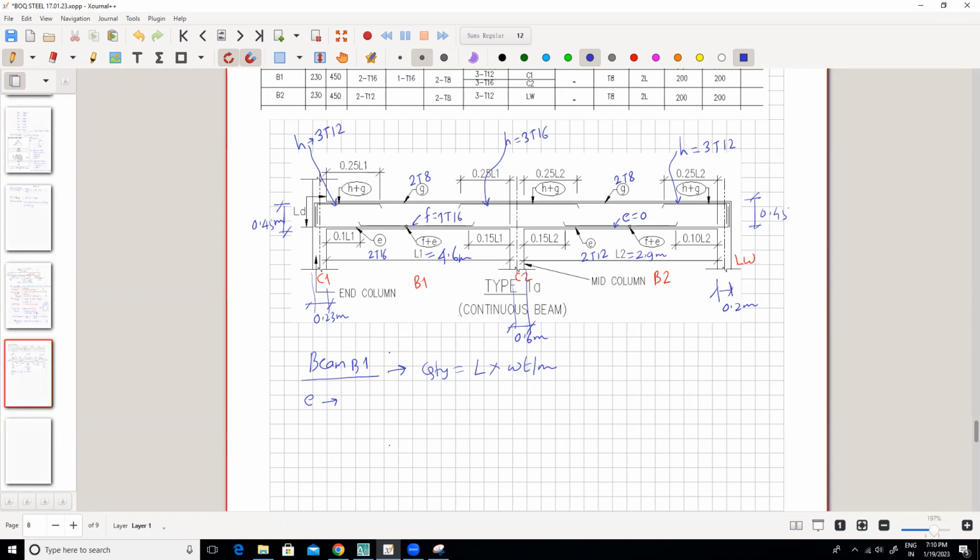Where we cut the bar E in this column. So we generally cut on the outer face like this, please keep in mind. And this E bar, we will curtail to this side, right? So that is important to understand. You should know where the bar will stop. So it will stop like this.